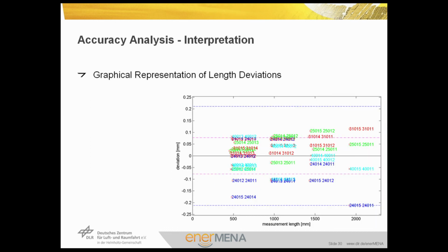An external accuracy analysis using the points on the calibration rods could do the following. You could or should compare the distances of the points on the calibration rods measured by the photogrammetry and compare these distances to the distances of the same points as stored in the calibration file. If you had a perfect measurement, the differences between those two distances would be 0, but due to measurement uncertainties, there are smaller or larger deviations.